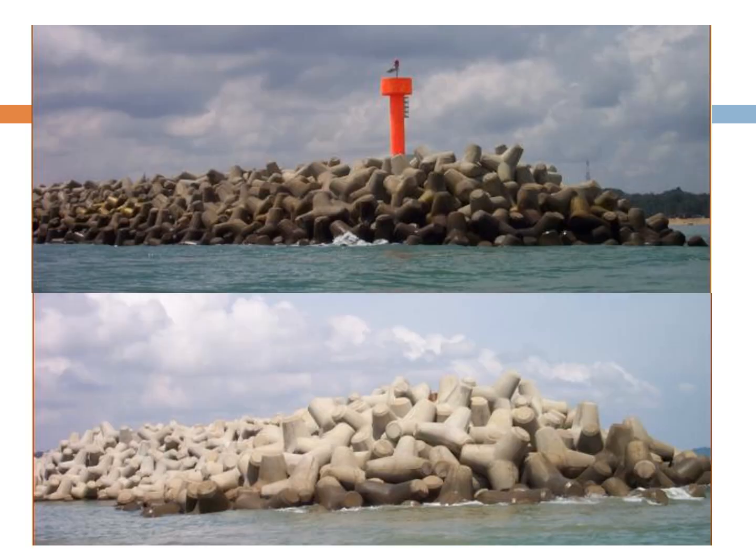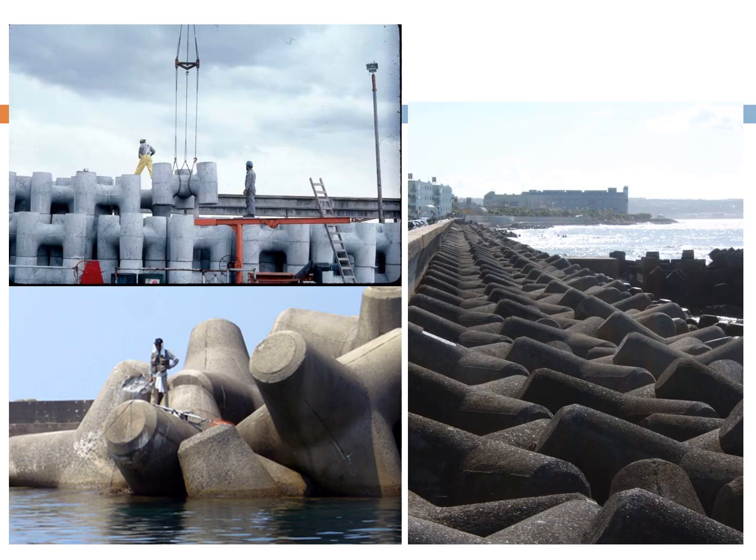This figure here shows an example of precast armor units which are dumped in place. Over here we see an example of precast armor units which are arranged in place to achieve higher interlocking properties and thus achieve a much higher stability coefficient. You can see the size of the armor unit compared to a human. Remember that if a quarry stone is used, the size required will be much larger due to poorer interlocking properties.